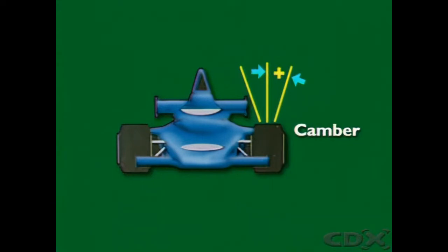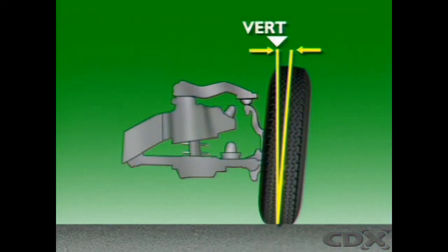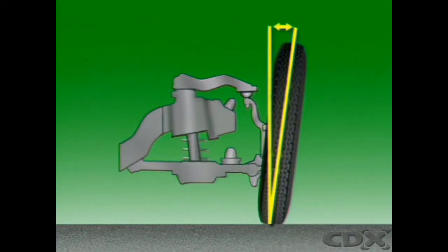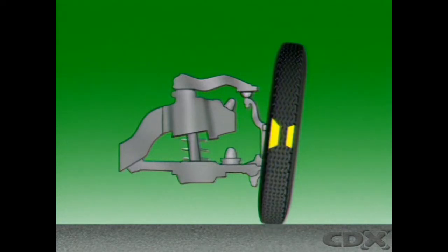Camber is viewed from the front of the vehicle, and it is the angle of tilt of the wheel from the vertical. A wheel that leans away from the vehicle at the top is said to have positive camber. A wheel that leans towards the vehicle is said to have negative camber. On earlier vehicles with narrow tires with a large diameter, large camber angles were used to bring the center line of tire road contact closer to the steering axis. It also ensured the vehicle weight was carried by the large inner bearing.